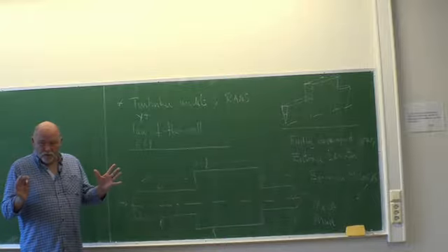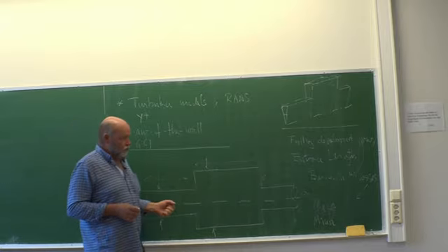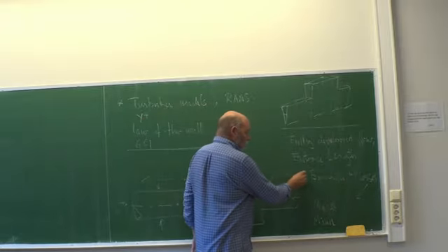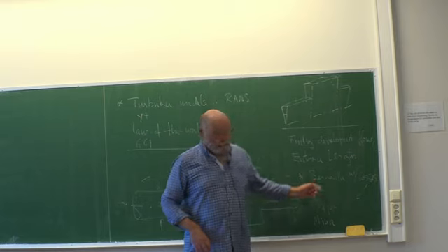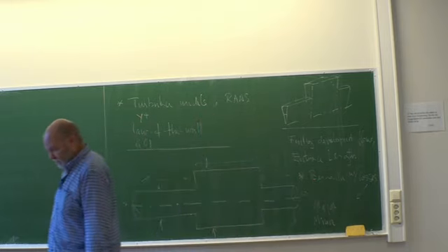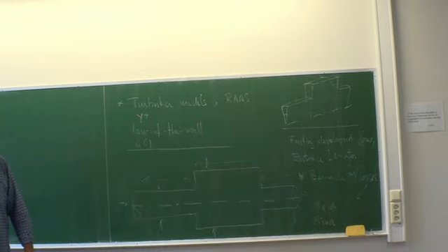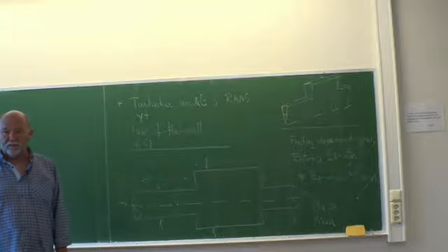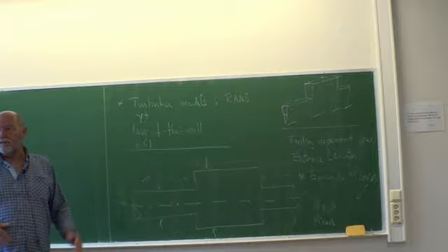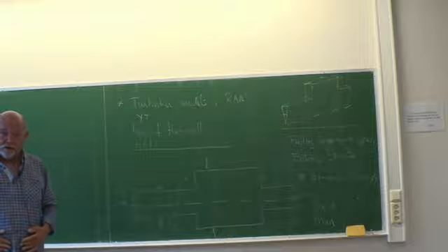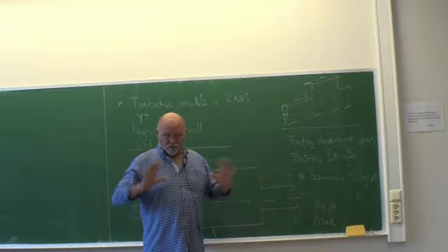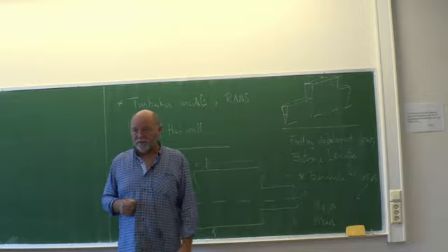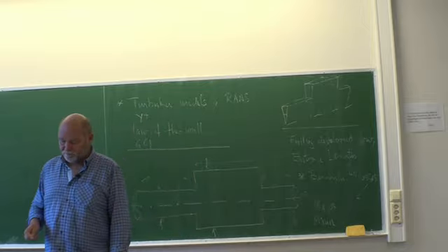So that should sort of be your main result, and then it should compare favorably to this one. Although Bernoulli with losses, that's an engineering tool. So they say typically plus minus 10%, 15%, and then it's still okay. So it's quite crude. But at least they should sort of be of the same order, or else you have done something very, very wrong indeed.